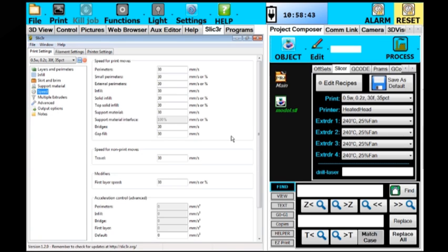If I'm printing with porcelain, I normally print at about 50 or 40 millimeters a minute. So that would be at 10 or 12 millimeters a second, or less than that even. Maybe 10 millimeters a second is 60 millimeters a minute. Something like that, or lower for porcelain and more dense, more viscous materials. And also material that is not going to set up as it's deposited. It needs to be fired, and you don't want to wiggle it too much as you're printing.